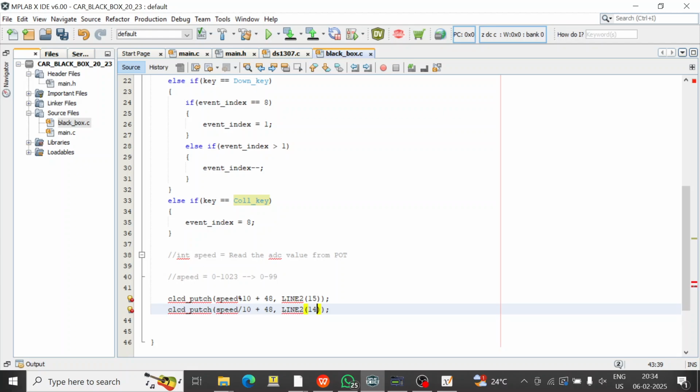That also is the same thing, Sanjeevi, what I'm telling you. Plus 0 is not possible. No, 45 plus 0, it will go somewhere, no? For a single digit value, you need to display 0, 0. If it is 7, then 0, 7 should be displayed. Yeah, ASCII of 0 is 48.